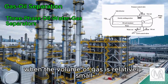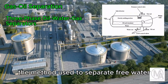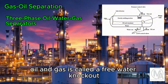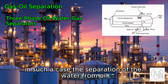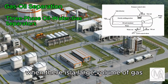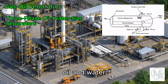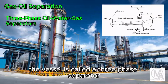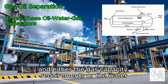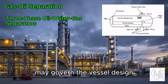When the volume of gas is relatively small compared to the volume of liquid, the method used to separate free water, oil, and gas is called a free water knockout. In such a case, the separation of the water from oil will govern the design of the vessel. When there is a large volume of gas to be separated from the liquid, oil and water, the vessel is called a three-phase separator, and either the gas capacity requirements or the water-oil separation constraints may govern the vessel design.